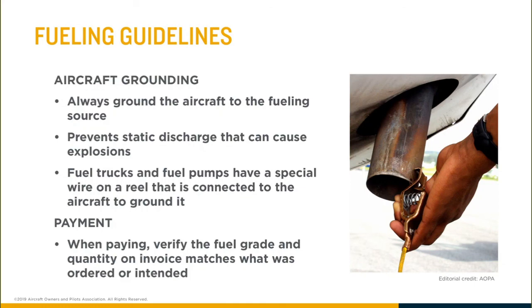Also, when you are fueling, you're going to want to ground it. So grounding means that any buildup of electrons or charges on the metal part of the plane will go down into the ground and not accumulate. If you took physics, you probably learned about static electricity, or you've just experienced that.